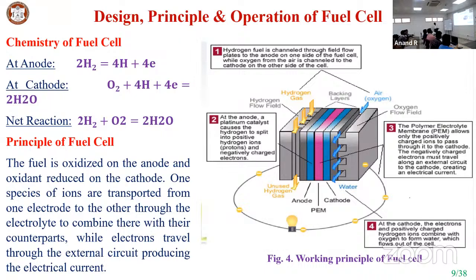Otherwise, the accumulation of water will reduce the electricity generation in the fuel cell. That is called water flooding, and it is the biggest problem in a hydrogen fuel cell. So for removal of water, you need to go for the design of the flow paths. There are different flow paths that people have tried: rectangle, square, hexagonal, honeycomb structure, many things. It is very difficult to fabricate a particular design before going for numerical simulation or computational methods to ensure how the hydrogen flows and how the water formed is removed continuously. So you need to select the proper geometry of the flow channel based on computational analysis. You model the different geometries and ensure which cathode flow geometry or anode flow geometry, as well as water removal, is best suited for getting good electricity out of each square meter of the flow path.